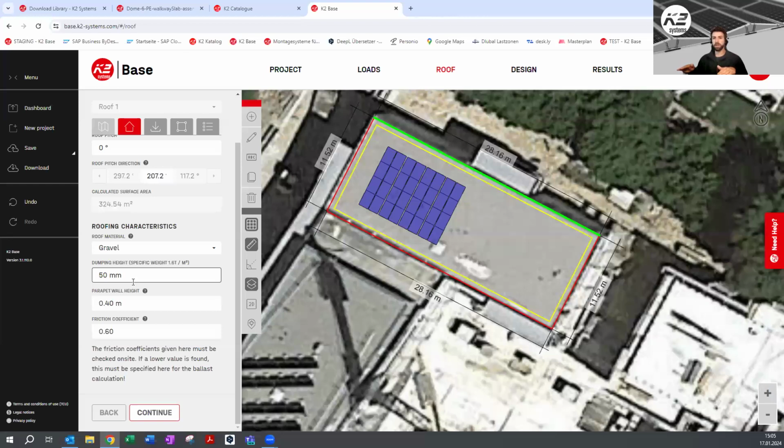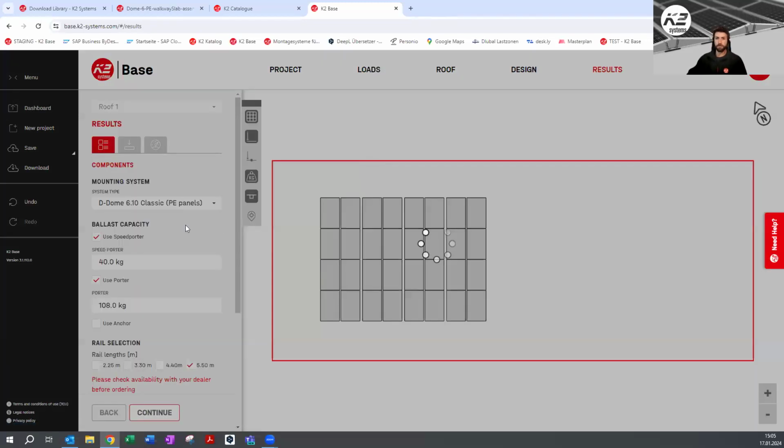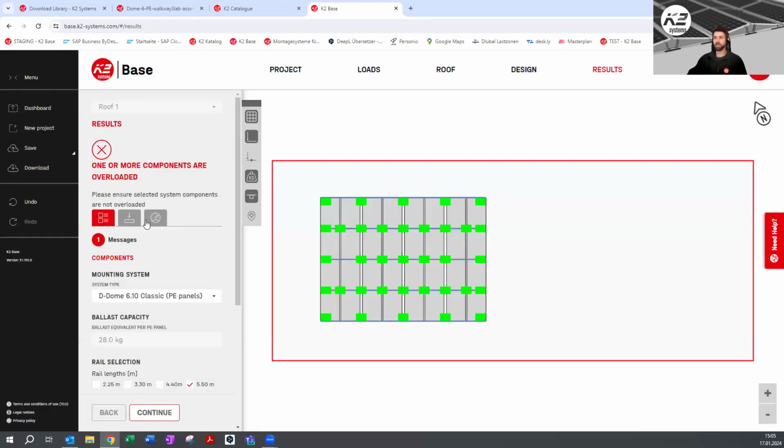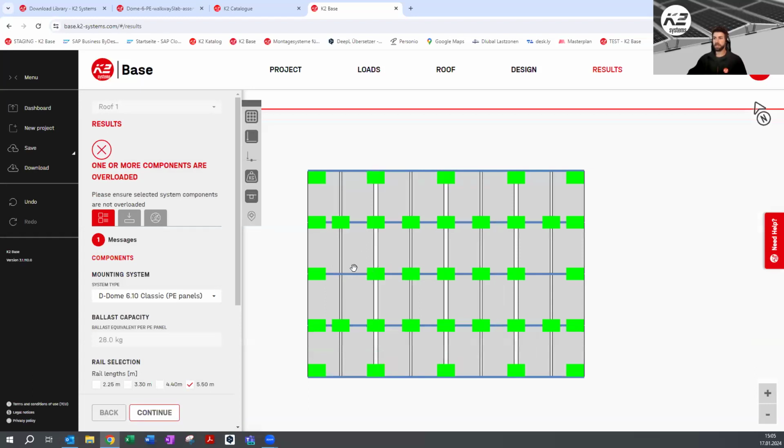And if you only have 40 millimeters on the roof, you can still push it together to have little hills, so you get 5 centimeters. It's a bit of a gray zone in between, but it works. If you have the 5 centimeters, you will not need any additional ballast anymore. Plus, there are some PE plates removed. There was one here before, and I think somewhere else maybe, but this one is removed as you have more weight pushing on all the other ones around. That's why there's no ballast PE plate needed here anymore. I think that's clear so far.